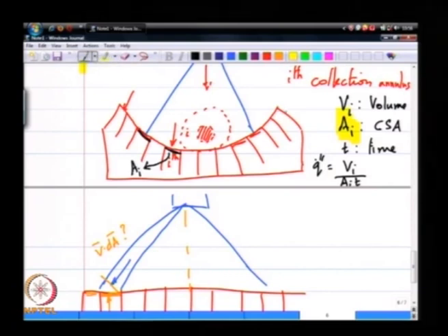Whereas, if I am looking at a small spray, say I am only 3 inches away, the entire spray width is only, let us say, 2 or 3 inches in diameter, and I have a sufficient resolution of tubes in that region, then an inline patternator may not be very far off from the circular patternator, but you do have this source of error.